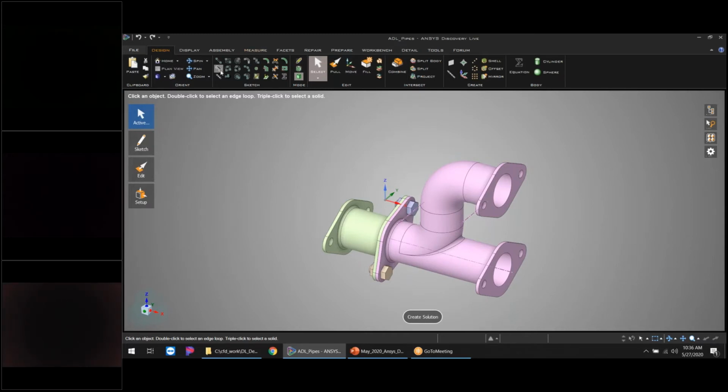What's really interesting is that inside of Ansys Discovery Live is a full CAD modeler. So we don't have to come out of the tool to go back into whether it's Creo or SolidWorks or Fusion or Onshape, wherever you're doing your CAD modeling. In this particular case, this is a step file, but I could, if I wanted to, create the geometry from within Ansys Discovery Live. For those who are familiar with Ansys, this is actually SpaceClaim, a lot of the functionality from the SpaceClaim modeler, including some of the direct editing, which we'll play with in a second.